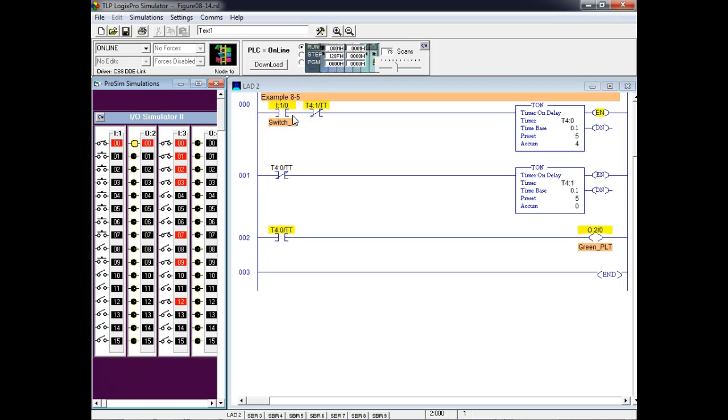One of the things they do is when you pull the E-stop, they want lights flashing indicating that it stopped. By the way, E-stop don't necessarily turn off all your outputs. E-stop should do what? Turn off all the outputs that could hurt people. So over there, if we do the E-stop, you'd see the lights on the front would start flashing. We use 2 of them, by the way. One of them's off while the other one's on, which would tell an operator that the E-stop button had been hit.